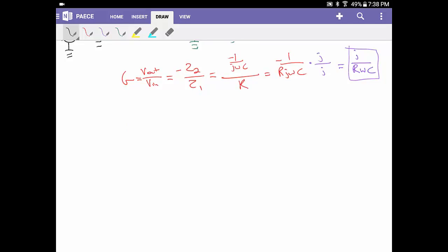our gain explodes. So our frequency response plot, or Bode plot, if we have frequency on the x-axis and gain on the y-axis in decibels, in this case we'd start out all the way up at infinity. I can't draw all the way up to infinity on this thing, but it would start out extremely high, and you'd really be limited by the characteristics of the op-amp and all the parts you're using, but that's for a later lecture. So ideally, you would have an infinite gain,